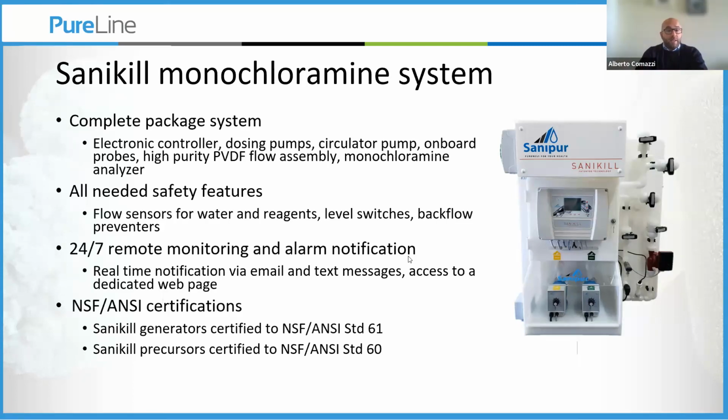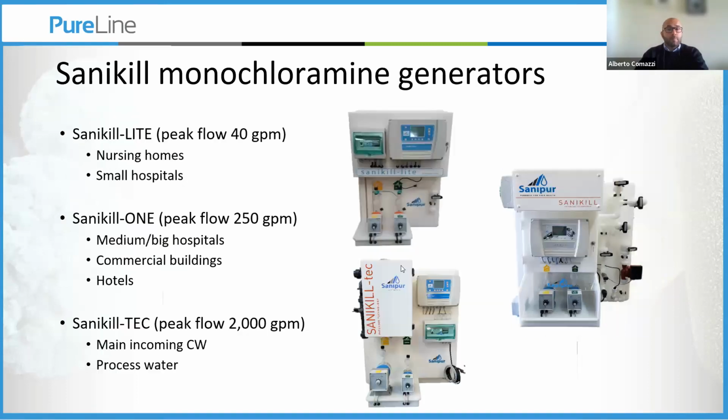The piping gets made in high purity PVDF, and all our generators have all the needed safety features, which I'm going to show you in a couple of slides, because 99% of the applications that we make are on potable water. All our generators are 24/7 remote monitored, and the operators have access to check the units online. All our assembly is certified to NSF standard 61, and the precursors that we use are certified to NSF standard 60.